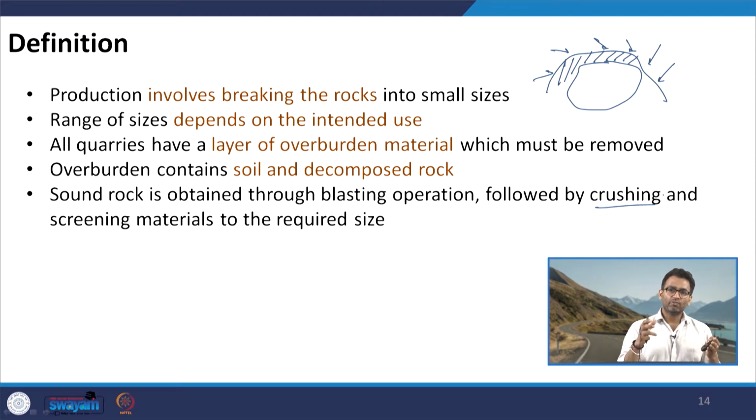Even after crushing, the aggregates break down into variable sizes. We have aggregates of different sizes. After screening these materials, we can store them separately with some size range together, let us say coarse materials together, fine materials together, and so on, so that we can conveniently use them during the construction process.